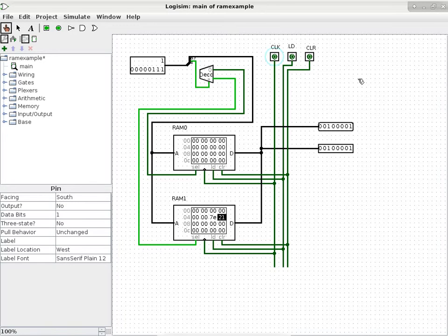So what we can do is to also pay attention to the falling edge. In burst mode, the RAM chip will do updates whenever there's a rising edge and also whenever there's a falling edge. But now things get a little dicey, because the processor now has to set up the data line safely before the rising edge of the clock line. This is the only amount of time you have to specify the new data on the data bus, because you need this to be done way before the rising edge.